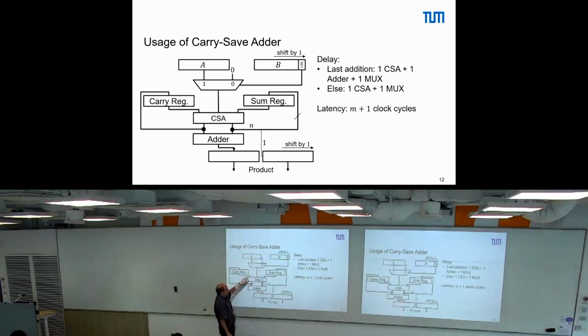Now, this one here is fast because the critical path here is XOR and OR. So three gates at most. This one here is slow because there are more gates involved, because we need the carry propagation from the very last to the very first. The carry propagation is here avoided. So in that sense, this here is fast, this here is slow. But this one here is definitely needed for the final, or something like this is needed for the final computation.